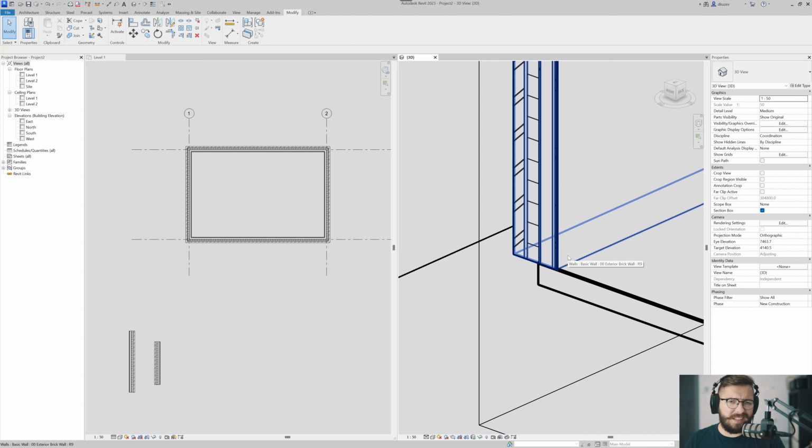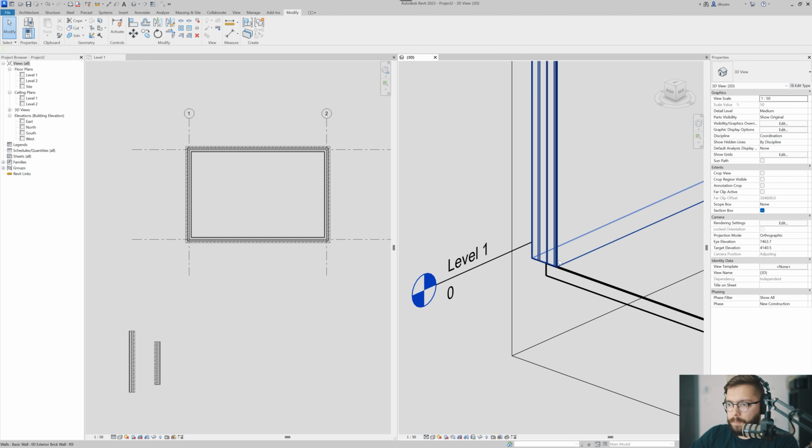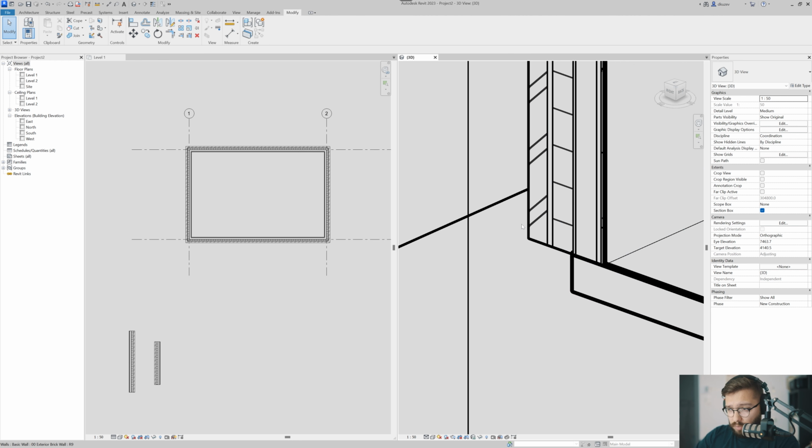This is usually used in cantilevers. You can see it quite often. You can see it in soffits where just the brick, not even the insulation, would come all the way down and it will sit on some kind of a structural lintel. But you don't need the whole wall to come down. You also don't need to create another type of wall, which is just brick, and then you fall into the whole issue of alignment and whatnot. But so what I want to do is I just want to make sure that just the bottom of my brick is able to go down.